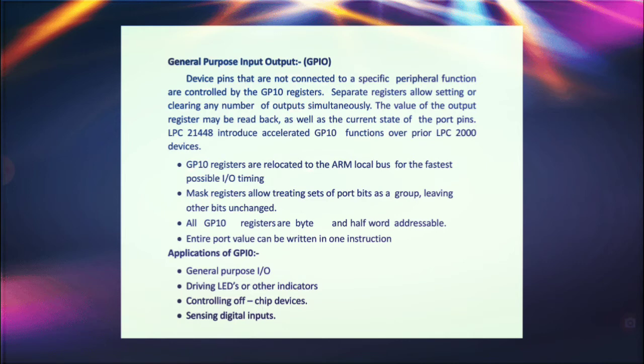General purpose input output, GPIO. Device pins that are not connected to a specific peripheral function are controlled by GPIO registers. Separate registers allow setting or clearing any number of outputs simultaneously. The value of the output registers may be read back as well as the current state of the port pins.